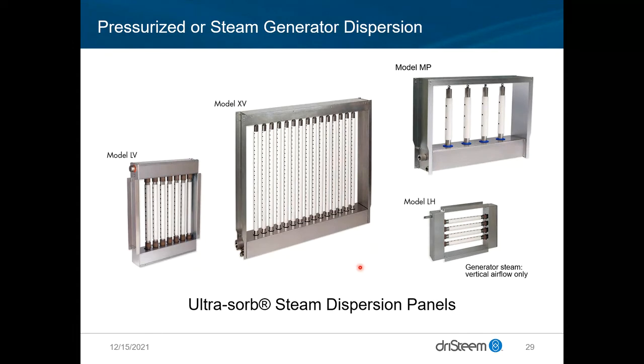Simple to mount, whether it be in a duct or air handler. There's all kinds of important things to keep in mind when you're selecting dispersion. But again, the idea being that these tubes have multiple orifices and are sized for the application, and pepper the air spray with multiple injection points to reduce your non-wetting distance, which especially in air handler applications is quite critical to make sure that we don't have to oversize that air handler to meet your humidification requirements.